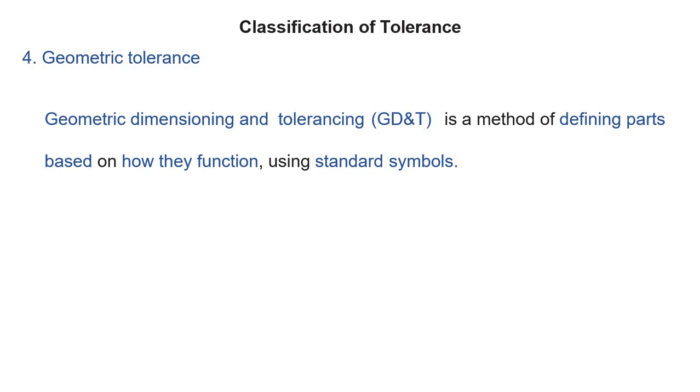In the last two or three tolerance systems, unilateral, bilateral and the third method, compound tolerance system, there are some disadvantages. If you have a hole or shaft that meets another part and is rotating or transferring power, and you only look at the unilateral or bilateral tolerance system, then it will not function properly. So in order to have proper functionality of the product, we now utilize GD&T symbols.